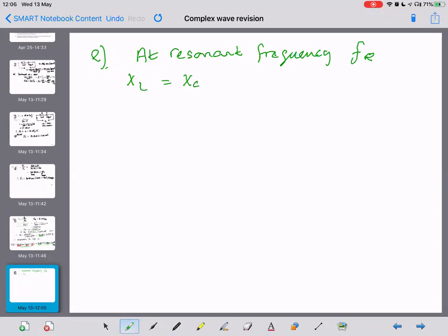Yeah, and it's saying prove or show that resonance would occur if we put a 4.17 millihenry inductor in that circuit. We're going to prove that resonance happens at the third harmonic frequency. So we know that we're looking at omega 3 is equal to 450 pi, from part D, and that's XL3 and XC3.